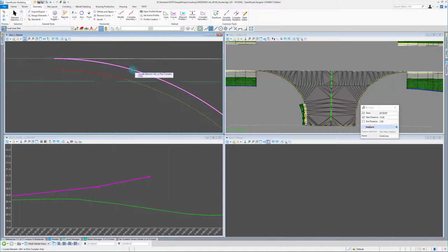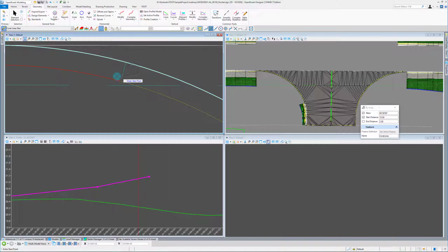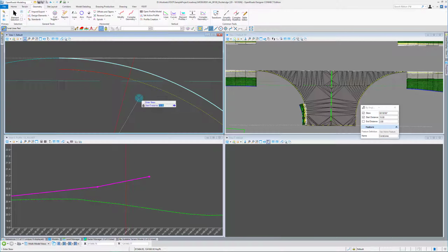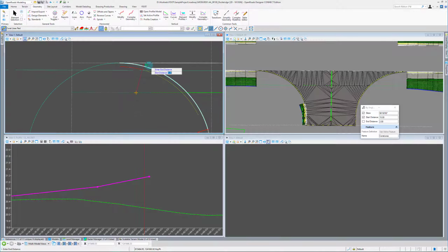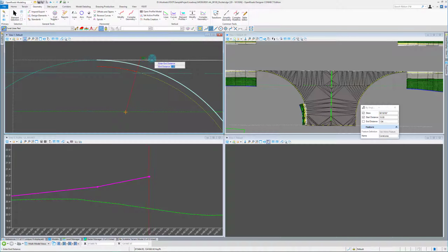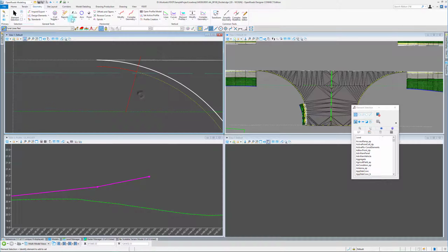We are going to do a biangle from element from our edge of pavement to the end of that line. And we're going to go 90 degrees for 15 feet. 15 feet doesn't really matter, but it's just a good round number. Make sure that we're extending that line beyond the limits of the curb ramp, and then we can just go to about 3. So now we're going to place our curb ramp civil cell. So I'm going to go into our model detailing and place civil cell.